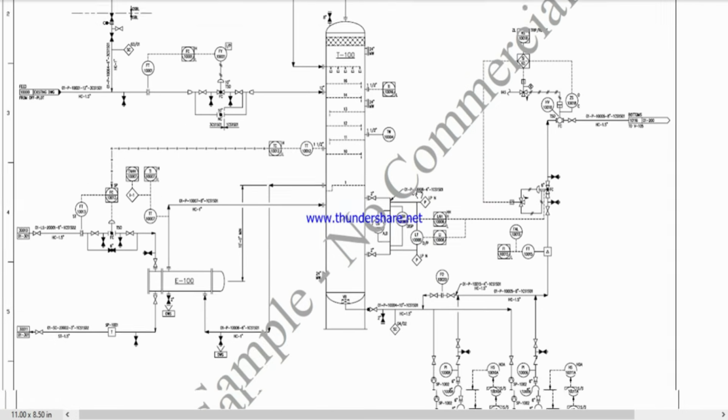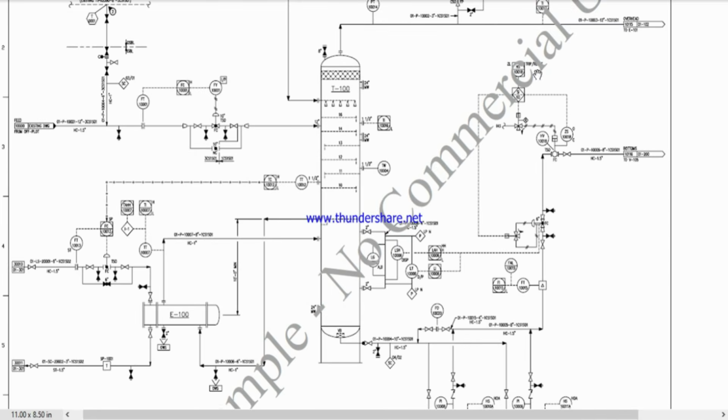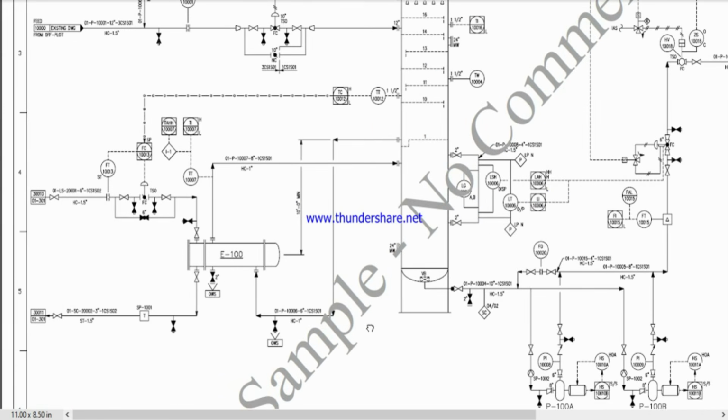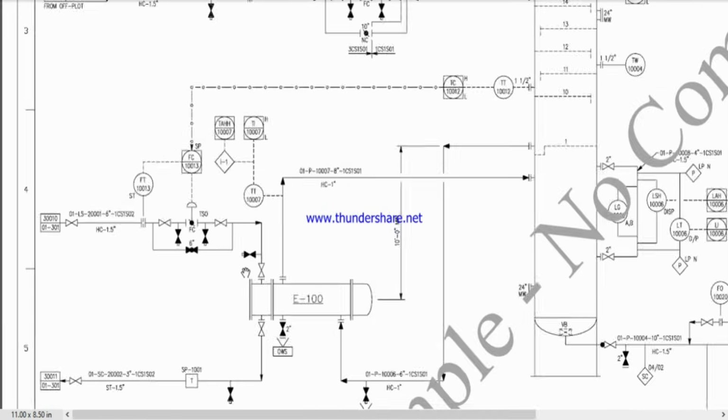Pipe branches feed more than one item. For example, when a pair of pumps feed one vessel, branch pipes are often connected to other pipes. For example, utility subheaders feeding several items, or a process pipe with a branch to another process pipe to meet a startup condition. Equipment items are bypassed. Control valves in pipes have a bypass loop fitted.